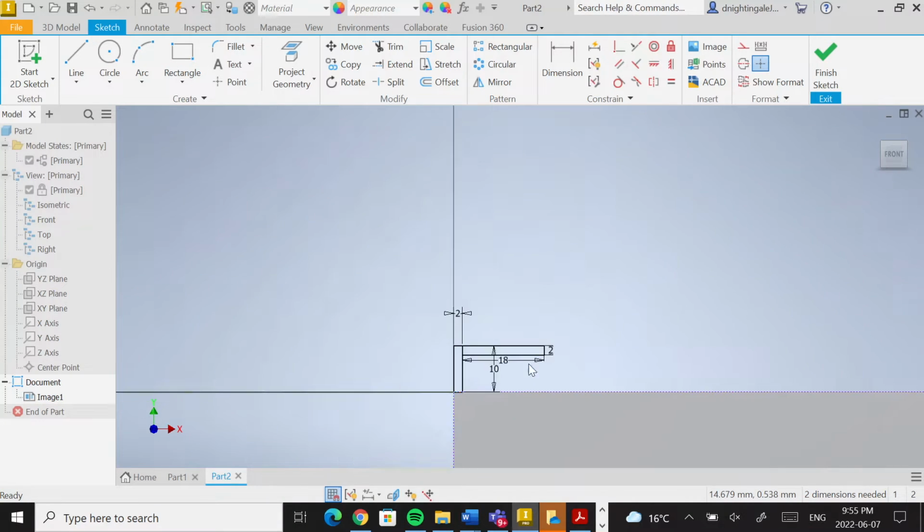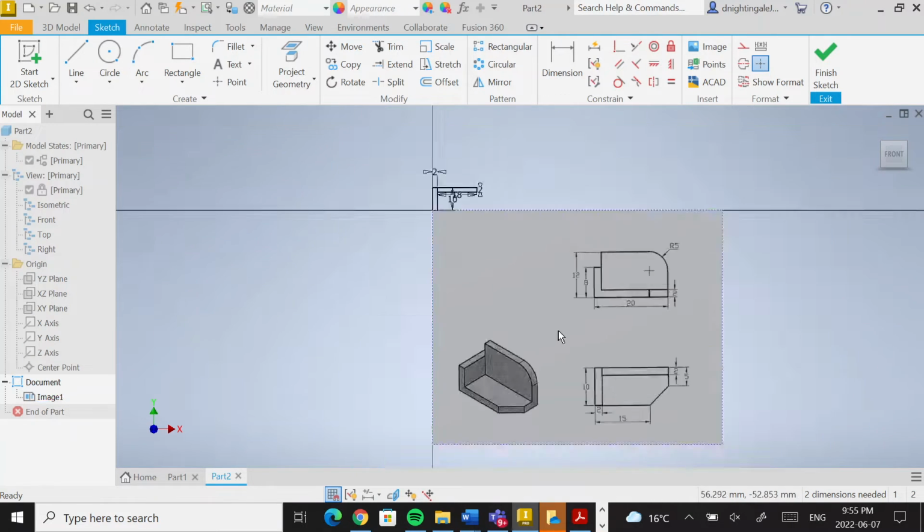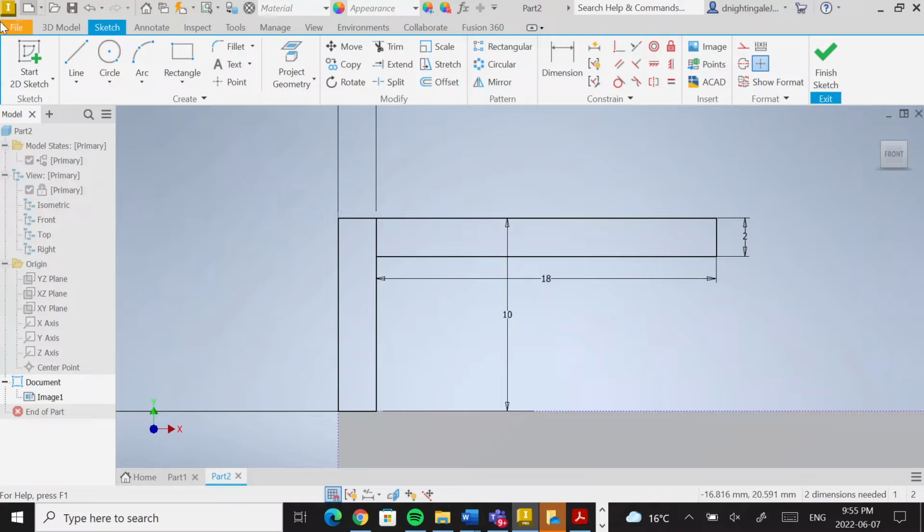Alright, so I'm going to finish the sketch. I know that it comes 3 more units of measurement and 3 millimeters down, 13 that way, so I'm going to add that in as well. I'm going to go to my line tool, make sure it's locked to that corner. I can come down 3. Press escape to get out of that command, back into the line. I'm going to go 13 horizontally.